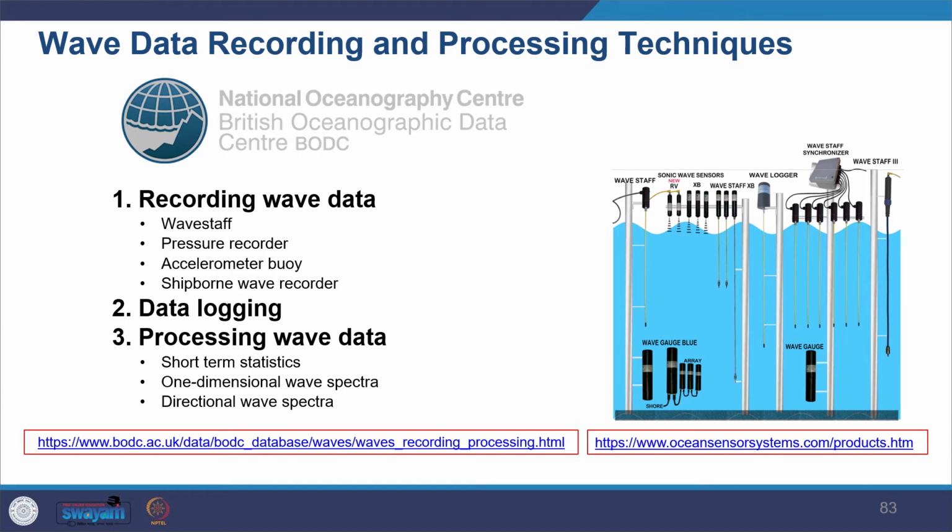So the data on waves, tides, and currents are usually taken from direct measurement. You can use wave recorders, tide gauges, and current meters. However, even though you can get all this data, the main problem is that when you use site-specific data, how much can you really generalize it to the larger area? So that challenge remains.